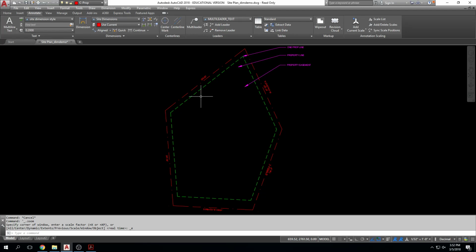Oh, yes, why do you think that is? Okay, select your viewport. There's scale factor 1 to 1. Okay, if you go back to model space, what is your annotation at? Oh, you have it scaled. Okay, so here's the problem.